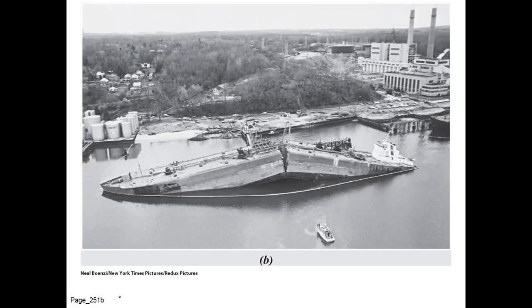Here's the classic case of a Liberty ship that had a low carbon steel shell, and then a crack propagated around the entirety of the girth of the ship. And like I said, this is a low carbon steel example, which we'll see is particularly susceptible to failure as a function of temperature. Specifically, it'll go from a brittle fracture at low temperature to a ductile fracture at high temperature.